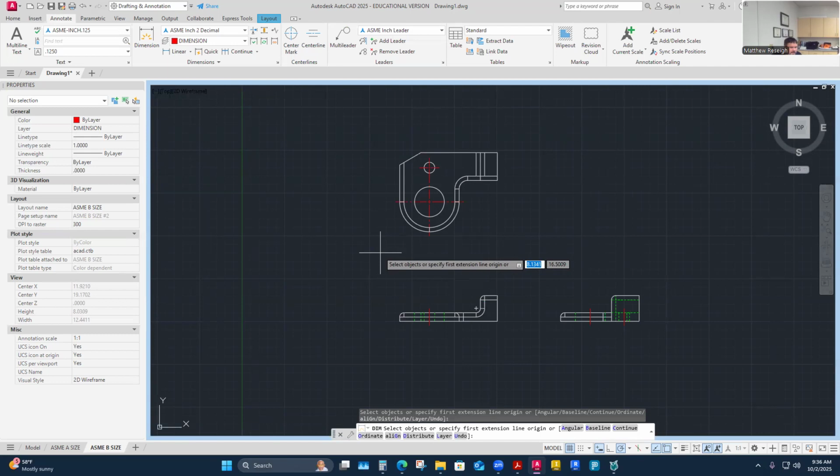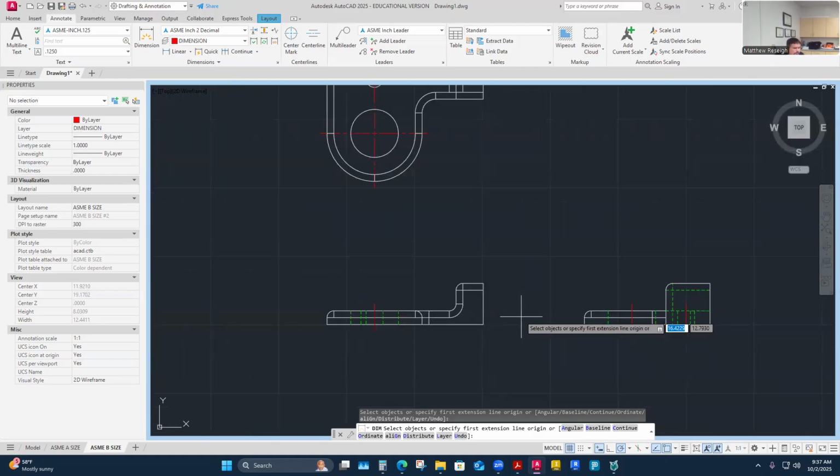So what I think of when I come into dimensioning is, once I start pulling dimensions, even the first ones I start pulling, I'm starting to establish those datums or those true surfaces to pull from. So if I take a quick analysis of this part, and I think, okay, if I pull from three different places on this part and base all my dimensions off of pulling from one, two, or three places, one of them that I'm definitely going to use is the bottom. Whatever I've used to set my part on in my front view is likely going to be the primary datum. Could be secondary, could be tertiary, but it's going to be a datum.